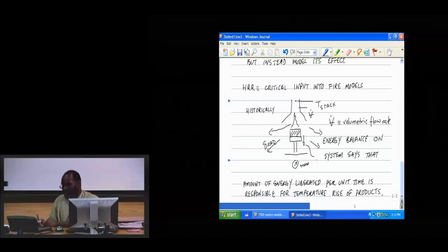And those parasitic thermal losses, I'd have to be really careful. Even this gas, I'd have to insulate the heck out of this collection system so that I don't have conduction and then later convection off of here. So I've got all these losses that I have to account for, and it's never really very well done.